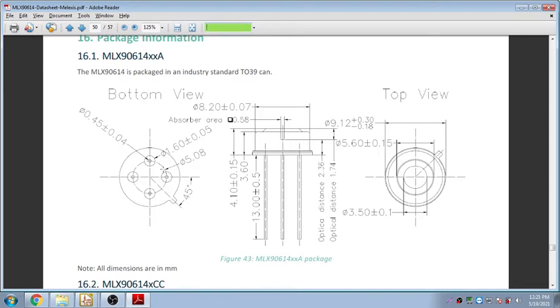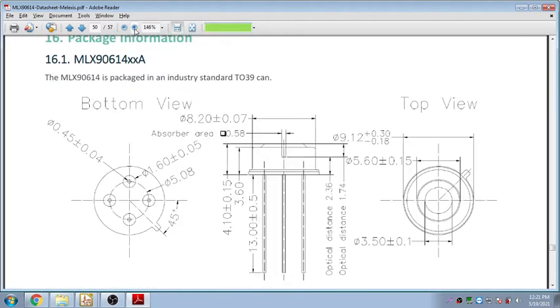If you look into this diagram, it indicates that the radius of this particular inner circle is 5.08 mm, the hole diameter is 0.45 mm, and the copper pad diameter is 1.60 mm. So anyway, this is not so important for us, but we can consider it.